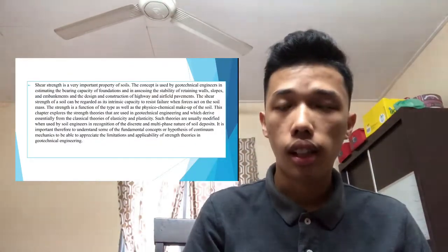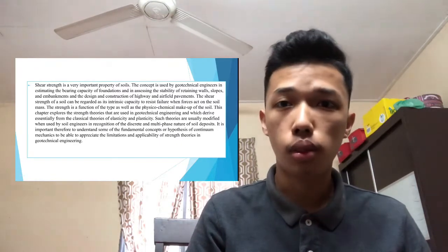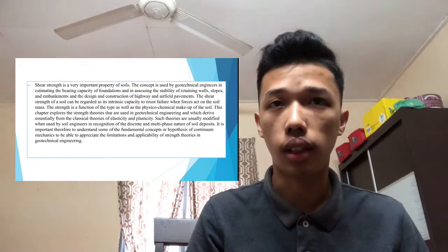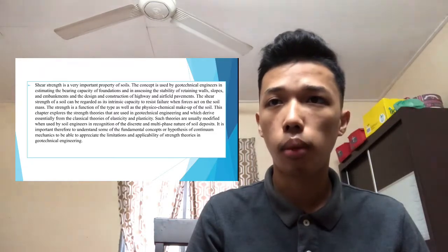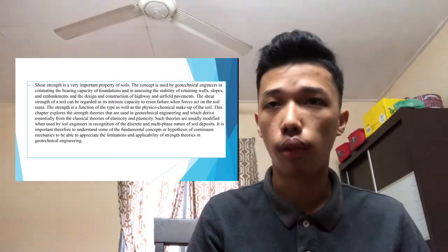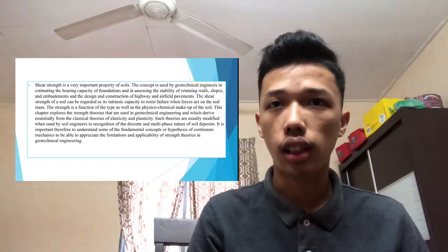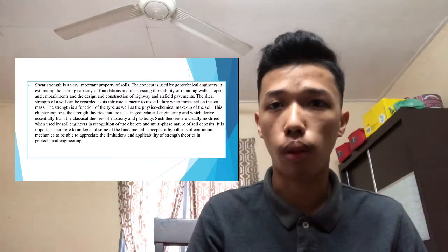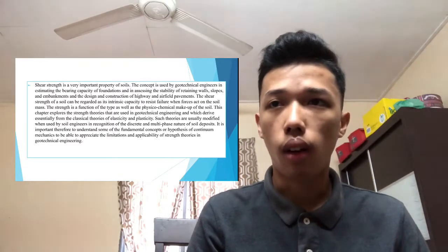Shear strength is a very important property of soil. The concept is used by geotechnical engineers in estimating the bearing capacity of foundations and assessing the stability of retaining walls, slopes and embankments, and in the design and construction of highway and airfield pavement. The shear strength of a soil can be regarded as its intrinsic capacity to resist failure when force acts on the soil mass.